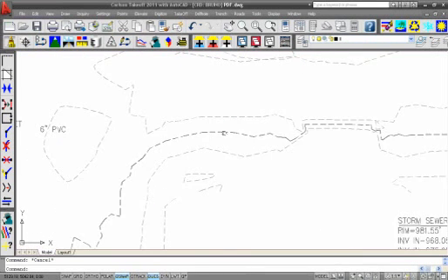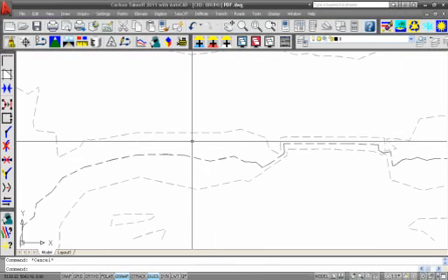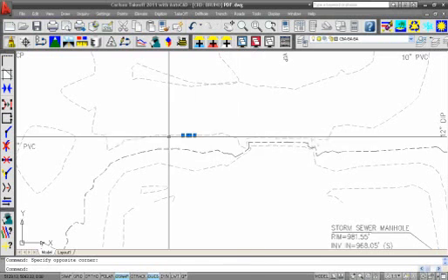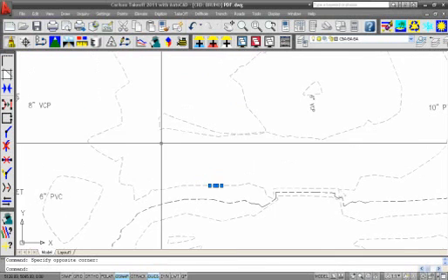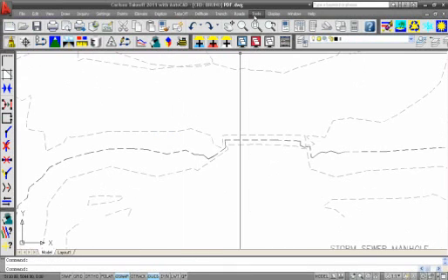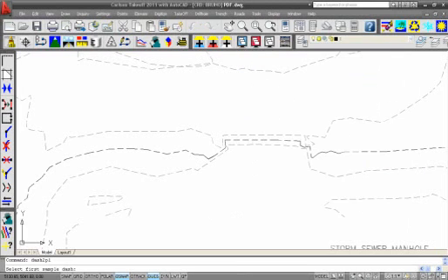Now, when we change those segments to solid lines, and we get rid of the blue bars, are we downsizing the file at the same time? It would probably reduce the file size because we're going to have fewer points comprising the contour lines. That's something we can look at. But the new routine is under Import/Export, and I'm going to say convert polylines to text. Or no, I'm not. I'm going to say convert dashes to polylines. That one's next. Okay, convert dashes to polylines.